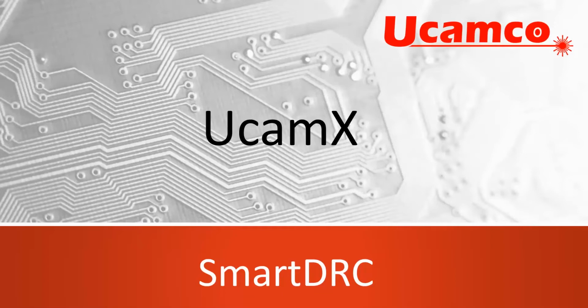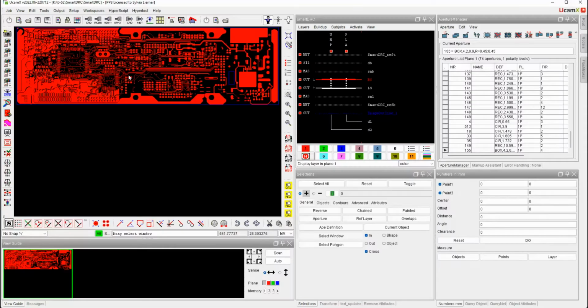I am happy to be your host in this video about UcamX SmartDRC and the wide range of possibilities it gives. It supports users checking and even repairing PCB data to optimize the PCB production flow and reduce the scrap rate. I will use a standard job to show how it can be used and how easy and variable the setup of the SmartDRC is. Let's start with the setup.